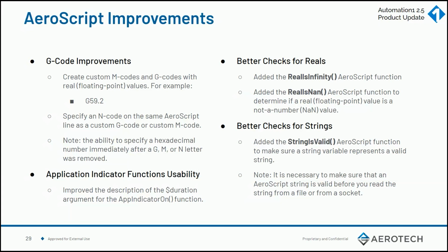If you use G-code, you know lots of G-code supports this dot notation. Well, we support it now for our custom M codes and G codes. None of our standard G codes and M codes have dot notation, but people want to customize and they like to use the dot notation for those customizations. Some of the NIST standards and G codes use dot notation.